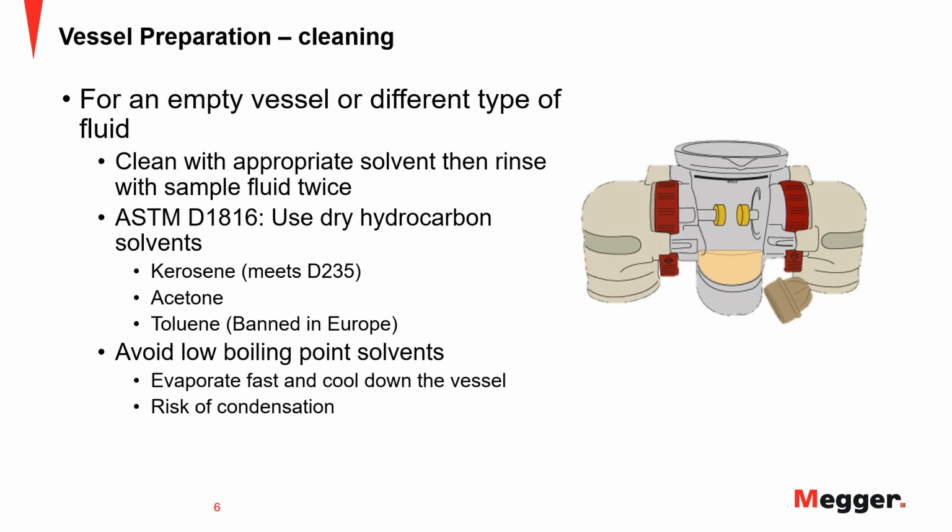And that cooling could then introduce the risk of condensation. So we must avoid using any low boiling point solvents, which is why ASTM recommends these three solvents above. Also, during any of the cleaning procedure, use only lint-free wipes to avoid any particulate contamination of the vessel.